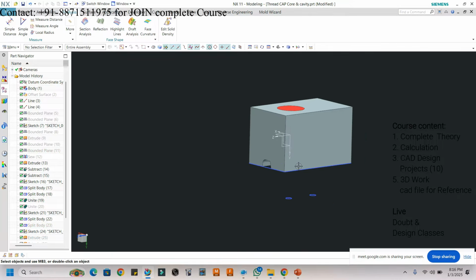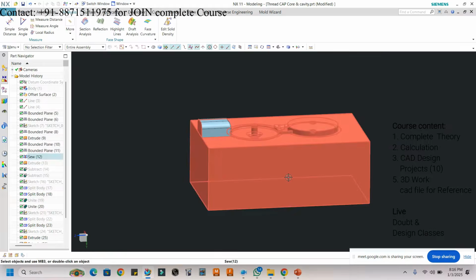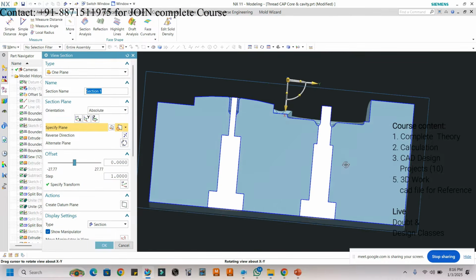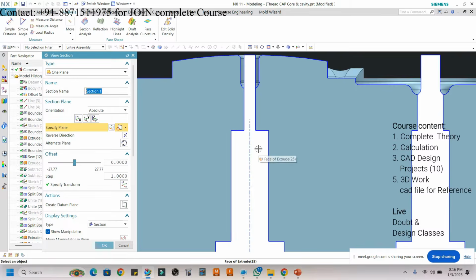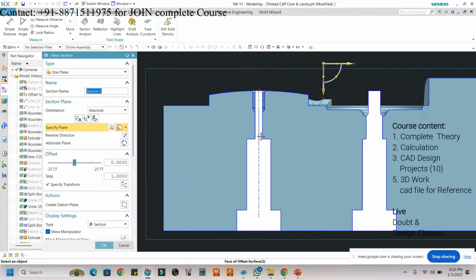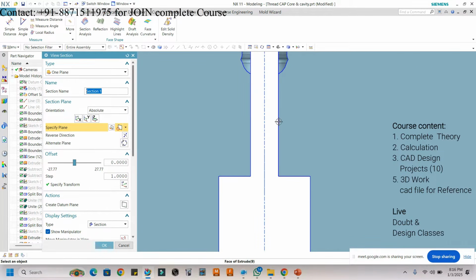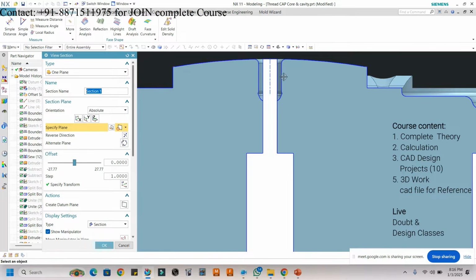See, now you can see that this is the cavity portion. Now what is this? Local insert. Why did I prepare the local insert here in the cavity insert? What is the reason? Because the diameter of this pin is very small, around 1.8 mm.